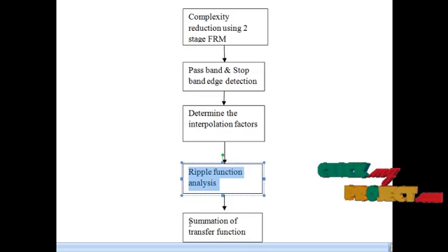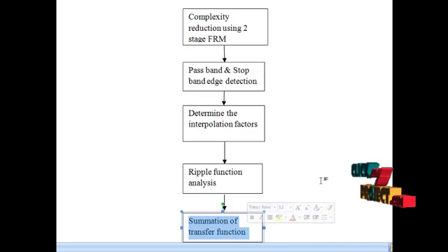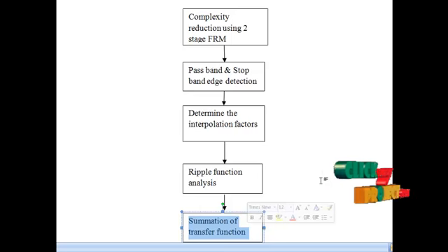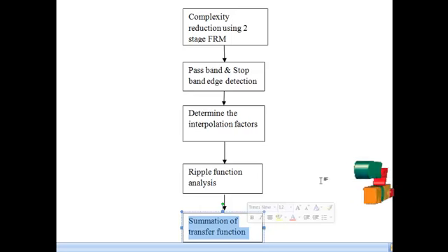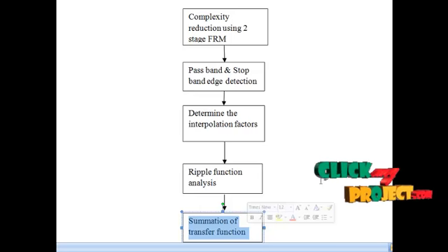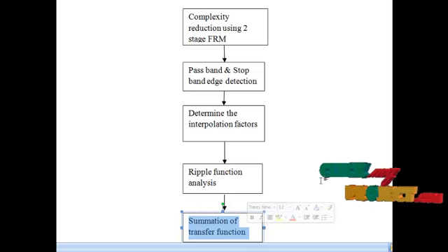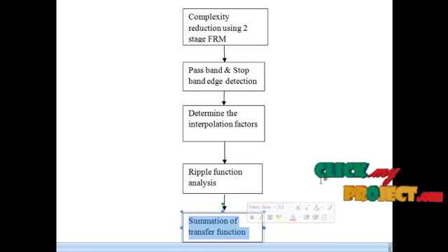The next thing is summing up all the transfer functions. Initially there are two switches. The input signal is passed through two filters with their transfer functions. Then we subtract the outputs of the two subfilters and store them in separate latches. That is, the output of one is kept in T1 and the other is kept in T2. The signals in the two latches are passed through a filter with its transfer function. This is added altogether to get the final output signal.